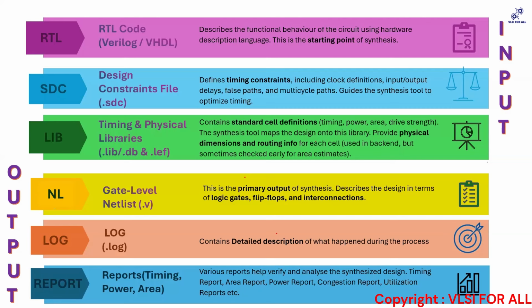There are different kinds of reports available. Some are standard files, but they are not automatically dumped. You have to make the tool understand that you need them, by giving report_timing, report_area, report_power. But since the industry standard is very huge, they do not follow only this. They make a wrapper around it and do a lot of scripting, because you cannot go manually through each report. The main report that every engineer looks for in the industry standard is called the QoR report.